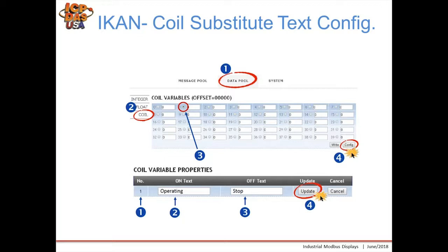The steps for doing it are: you go to the data pool tab in the web browser, select the coil variables, and you select with the radio button the coil variable you want to configure, and then you click the Configure button in the bottom right corner, and you type in your on text and your off text, and then you simply click Update. Now when you want to display this coil's properties or value, it will substitute the on text or off text for a 0 or 1 condition.